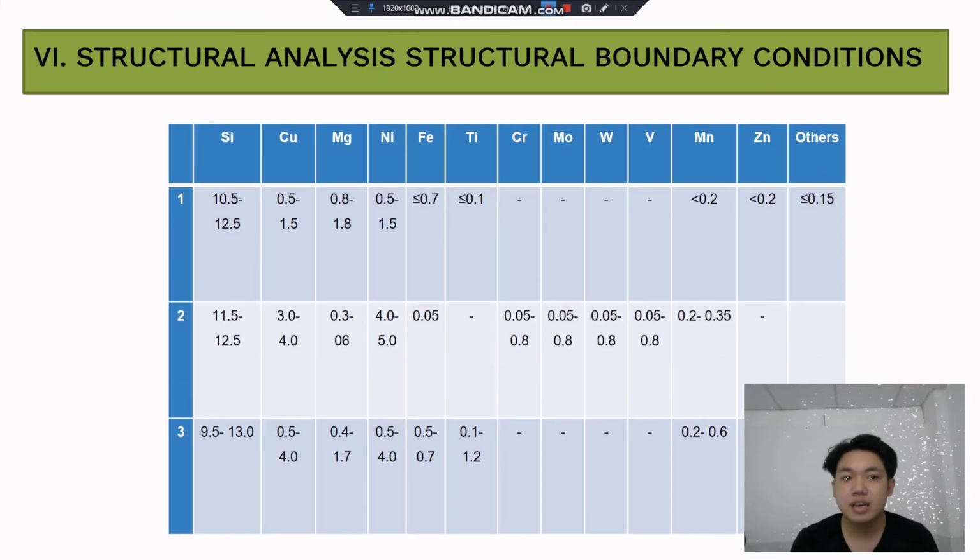And next, I will present the structural analysis and structural boundary conditions. As a basic alloy to manufacture the test samples, the near-eutectic aluminum silicon alloy labeled AK12 was taken. The table shows the AK12 alloy chemical composition, a general view of near-eutectic alloy composition, and the alloy composite, which is the final result of the work carried out and which led to making the new piston. First, AK12 alloy for the forged piston, tested composite silicon alloy, and generalized composition of near-eutectic aluminum silicon alloys.